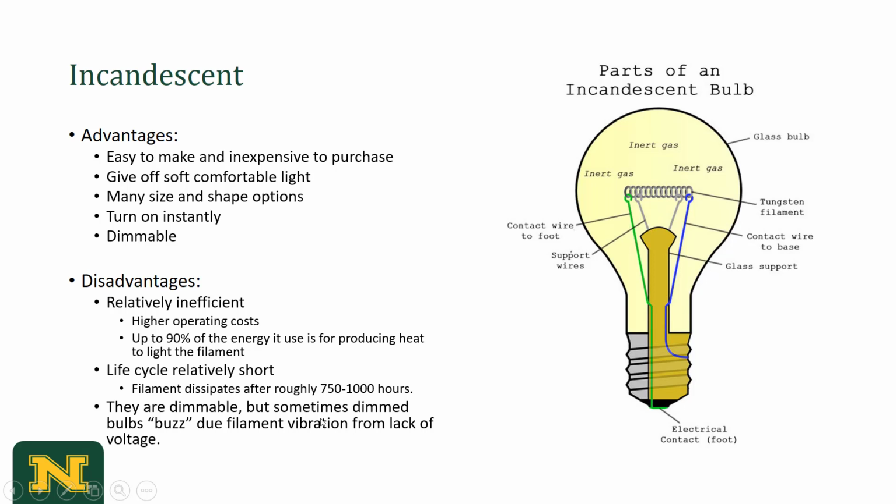It's also got a relatively short life cycle, because as that filament is heating, it's constantly slowly wearing away. They are also, like I mentioned, dimmable, but sometimes that dimmed bulb buzzes due to that filament vibration. So if we're giving it a little bit less current coming through, it's not vibrating as fast with the wavelengths. So you're hearing that buzzing sound.